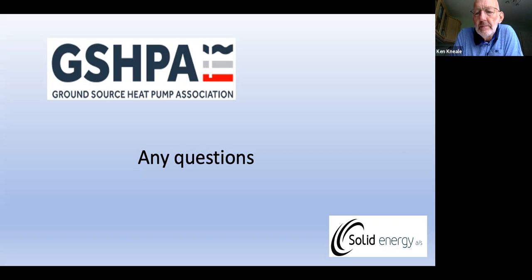But with all of these, if there are further questions that come up after this session, then please do feel free to email them across, and we can field them out to Ken or to anyone else to answer. From Michael, at 20 degrees C source water temperature, so going back to mine water, it will be possible to preheat the ventilation air directly for a building. And the heat pump could be used to deal with fabric heat loss. That's a statement. Any comment on that, Ken?